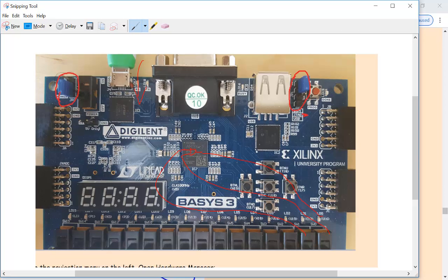If you look here, it's a QSPI. The memory chip at the bottom is connected to the FPGA chip using the SPI protocol. So it's actually programming this FPGA using the SPI port. And you have to reset it or reprogram it by pushing this push button here to program the FPGA. If you keep this jumper wire over here on the top, it's going to keep the memory chip communicating with the FPGA in the future, even as you power it off.